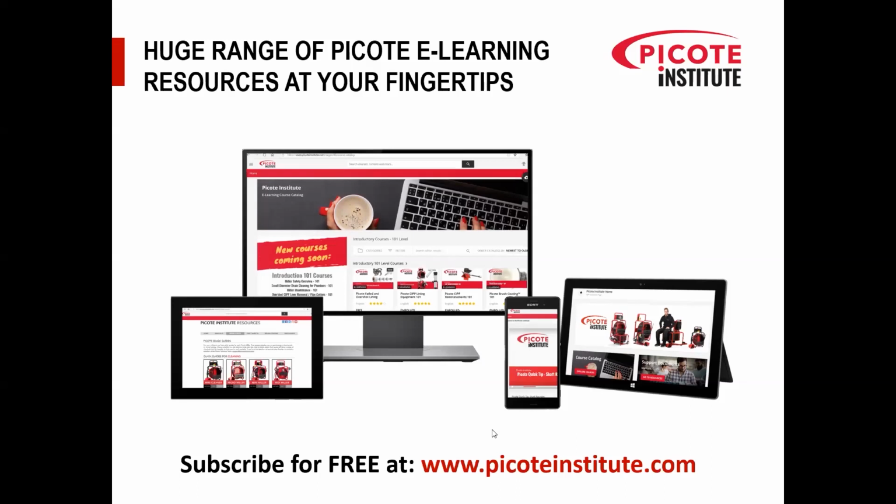Okay, if the miller's left out and he's asking for a friend, so the miller's left out in the rain all winter, how do we get it running again? If the machine's been left out, you need to make sure that it's dried off. We always say if the machine hasn't been used for two to 3 months, what you need to do is remove the shaft and lubricate the shaft.